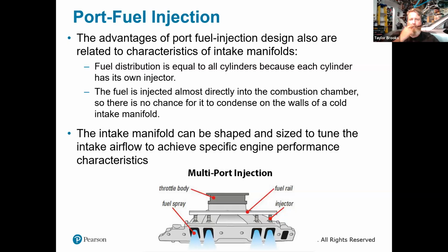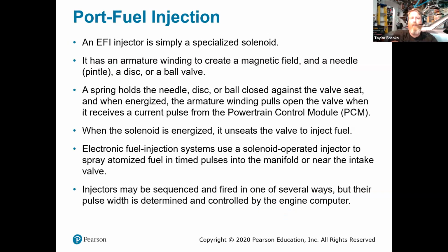Basically, between 2 and 3 inches, or 70 and 110 millimeters, away from the intake valve, we are going to have a fuel injector placed, and it will spray fuel with the incoming air being drawn into the intake, down during the intake stroke and into the engine at that point.